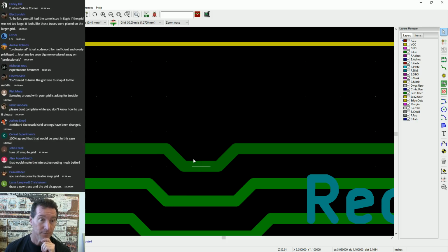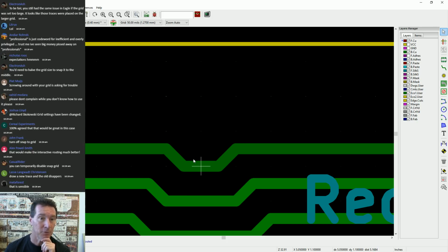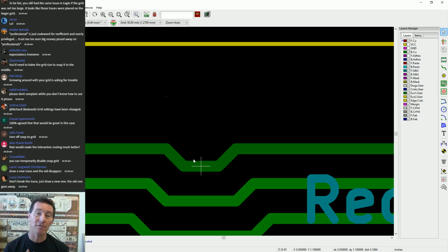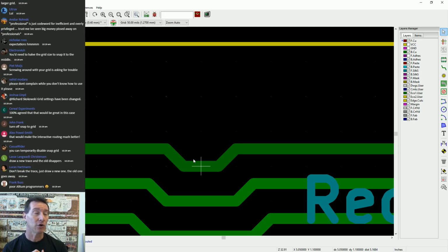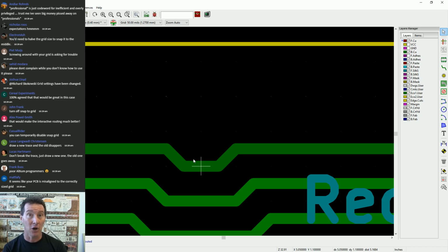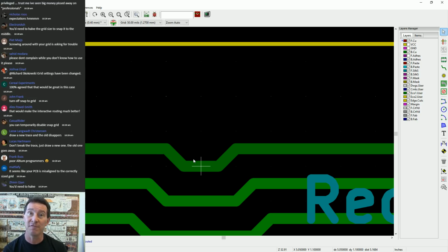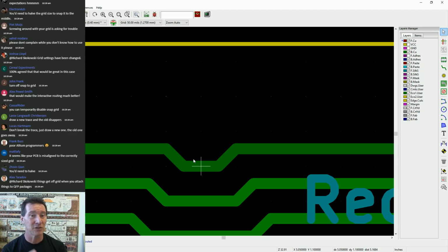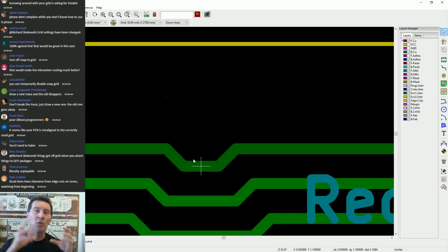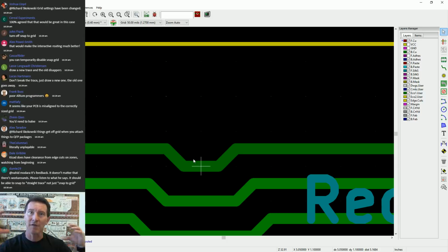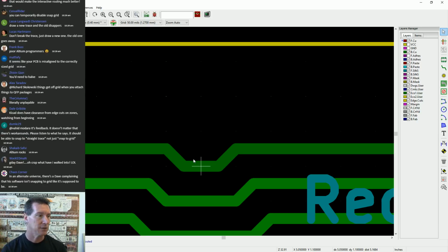Richard asks a good question. Why did a professional PCB designer put traces off grid? Well, I didn't design this board, but there are many reasons why you would do that. When you're designing a board, especially a complex one, you are changing your snap grids and visual grids all the time for various reasons that I won't go into. Like, you're mixing imperial and metric components, surface mount and through hole. You're doing all sorts of other stuff.